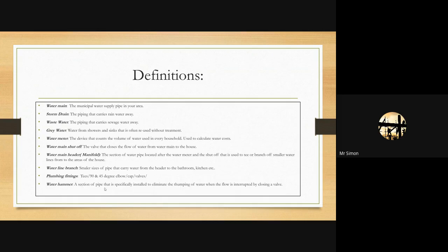And a water hammer is an interesting thing. If anybody's lived in an older house, you'll know sometimes that when you turn the water on or off, you'll hear the water go bang and you'll hear the pipes bang. That's the water flowing and then stopping, flowing and then stopping. The stopping slams. You're shutting it down really, really hard.